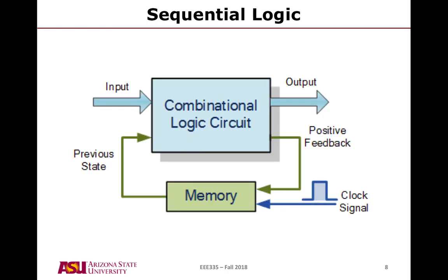Now, in essence, sequential logic is actually made out of combinational logic circuits, and what we do is we will tie the combinational logic circuit in a feedback loop, so the outputs will somehow be fed back to the inputs, and that function, that tie back or that architecture will allow for memory. Now historically this was done without a clock, so we can actually implement memory without a clock, but as you will see in this module, these memory circuits have evolved to be clocked systems.